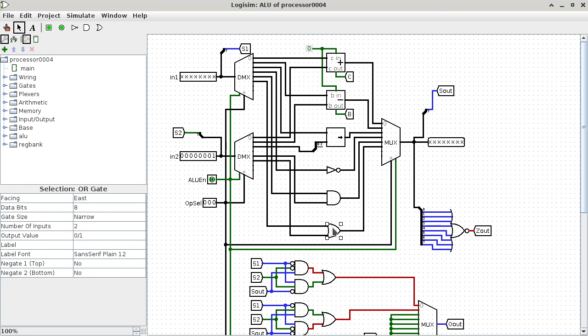So now, if you're asking, so how does it multiply, divide, sine, cosine, and all kinds of stuff like that? It can all be done in software. So given these operations, I would say AND and OR are not even needed in most cases. So given just being able to add, bitwise NOT, right shift can be useful, because subtraction is technically not needed.